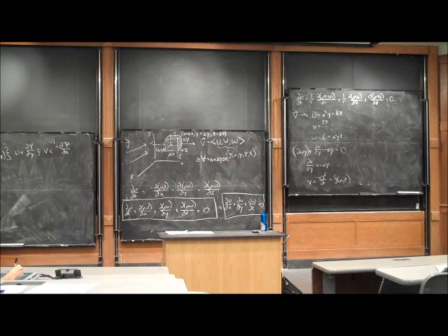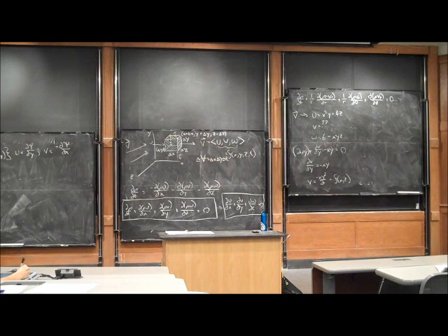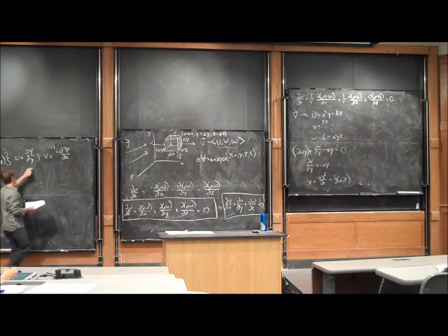Because if we then apply conservation of mass to this, I see that du dx now becomes del squared psi del y del x, plus dv dy, which is minus del squared psi del y del x, is equal to 0, and this is true. So all we've done is perform a mathematical trick that satisfies the conservation of mass.